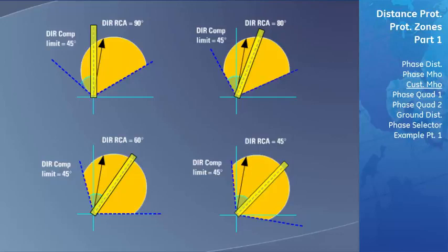As you can now see, the D60 is very flexible and allows for the Mho characteristic to be modified in many different ways to tailor the protection to fit your needs. Simply by changing the comparators that we discussed in the previous sections, you can alter your distance characteristics to fit most any power system conditions.